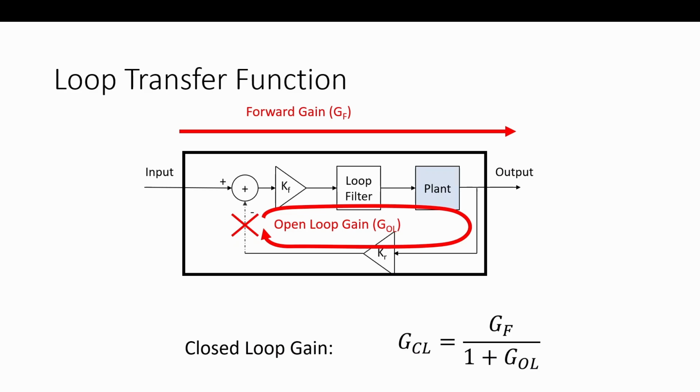If I saw it was instant, and really, everything has poles in it. You don't want to deal with a million poles if you're dealing with a low pass system, and these poles I'm talking about are 100 times higher frequency, we can ignore them. It's good to be able to recognize that as we simplify the system to its most basic form. It could be anywhere from 10x to 50x, depending on how sensitive we are.